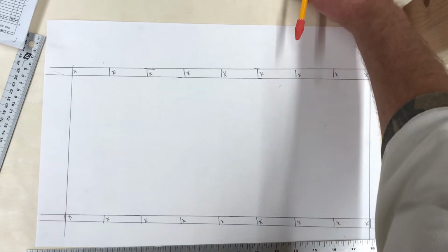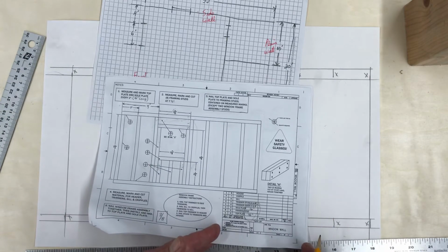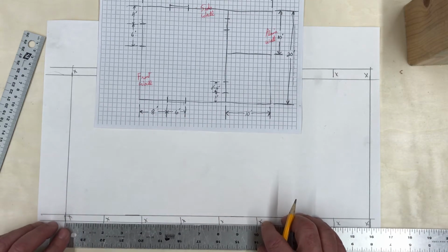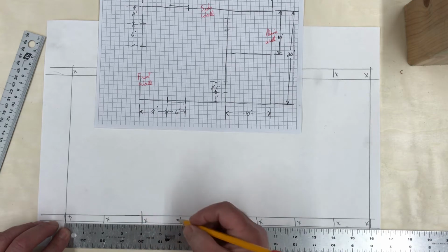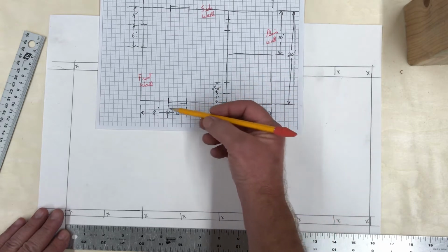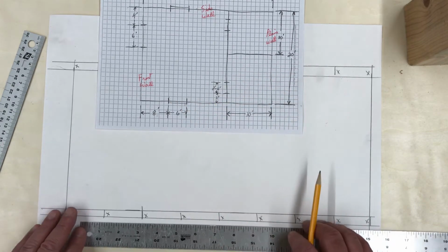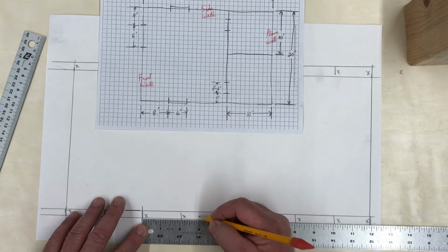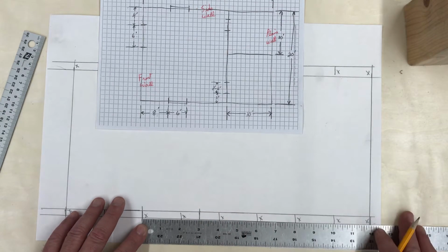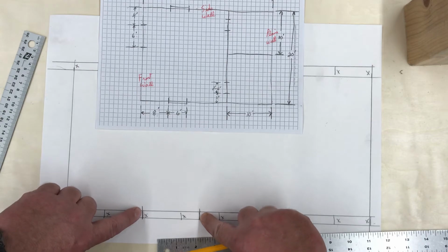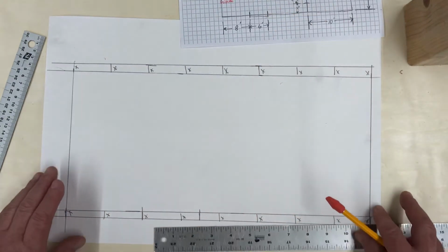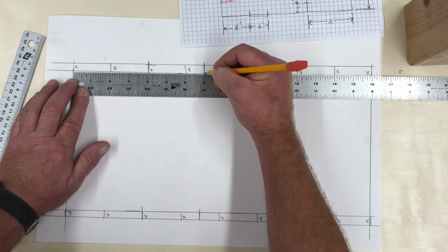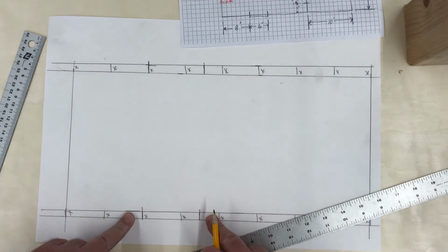Now I need to go back to my rough sketch, or you could go back to the plans that I gave you. Mine says 8 feet from the corner. So what is half scale? It's 4 foot. All right, that's 4 foot over. Now, how long is my window? Well, it's a 6-foot window, which is a rather large window, like a big bay window. So half scale, 6 foot would equal 3 inches. Now I know from here to here is my rough opening. I want to do that at the very top too, so I get some nice straight lines. 1, 2, 3. So there we go. Between those lines, that's where my window is going to go.